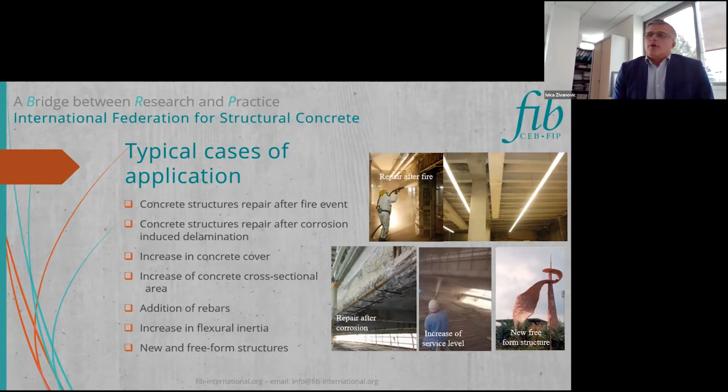Of course, there is also reinforcement, because sometimes it is needed to increase only the concrete cover, but also sometimes the cross-section area, with addition of rebar and increasing of flexural inertia. And sometimes we can also build a new freeform shape structure, as we can observe at the right side of the slide pictures.